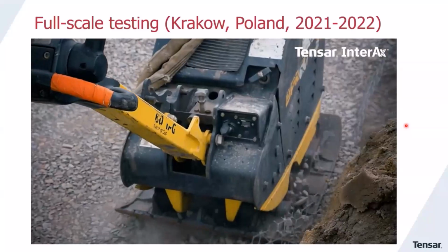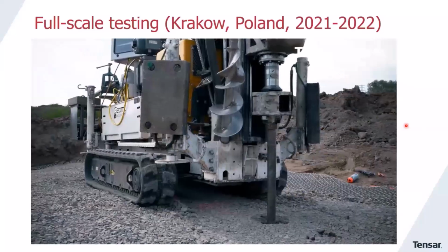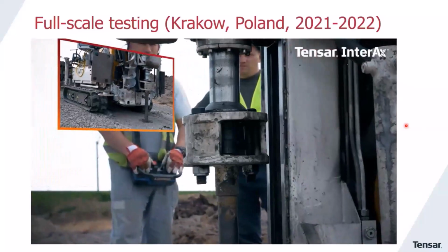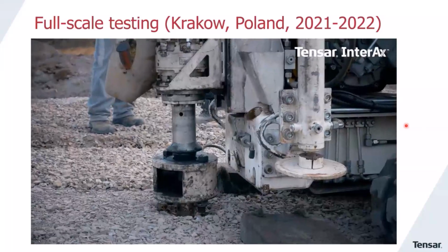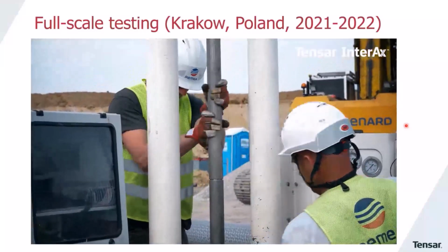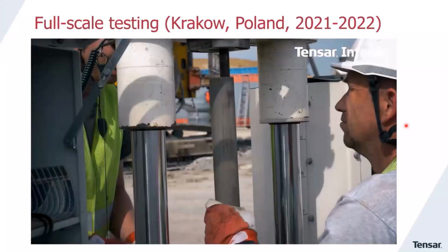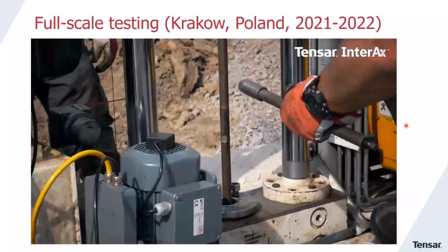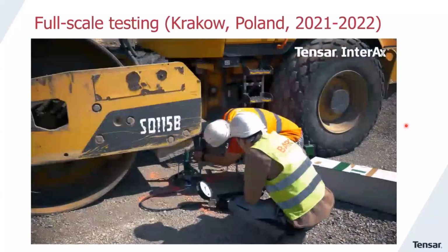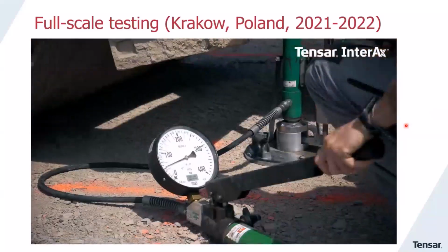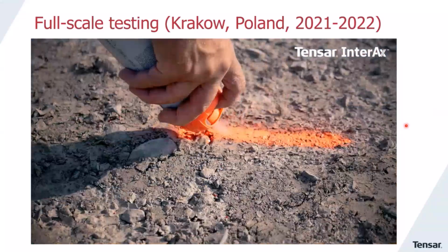So in this validation trial, we took particular care to simulate real life circumstances. What you saw there was the rolling out of the geogrid and the placing of the crushed rock material. What we're looking at now is some soil investigation soundings being taken through the constructed granular raft, so we have actual behavior after compaction. Of course, also here we did some plate load tests to ensure that the modulus was known.